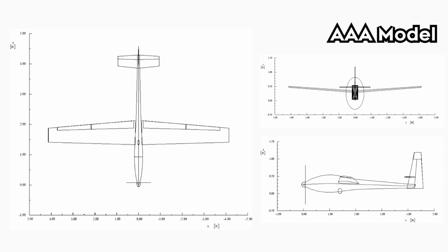The horizontal tail is mounted just like with the vertical tail, mounted at the end of the fuselage. The horizontal tail is mounted slightly above the fuselage on the vertical tail. It features an elevator that runs the entire span of the horizontal tail, and that's used for pitch control.